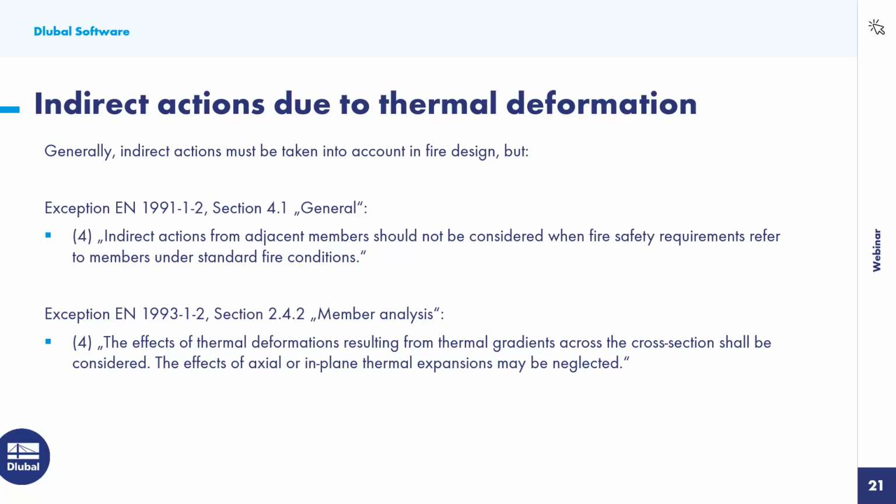And because the formulas that we use to determine the heating of our section always assume that we have a constant heating over the section, we don't need to take into account the thermal deformations at all.